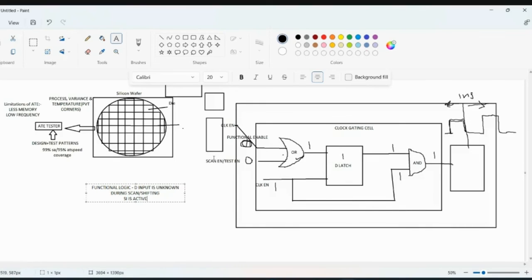Now, the usage of clock gating cells will be like this. Either in the OCC, you will see a clock gating cell as part of your OCC, and you will not be able to do anything on that. The OCC clock gating cell is the OCC clock gating cell; you will not touch it. There will be functional clock gating cells and DFT inserted clock gating cells. So in total, how many do you have?